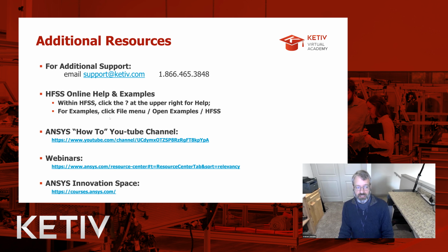And then in addition, I wanted to alert you to the HFSS online help. The little question mark at the upper right is very helpful. And there are also, if you are within HFSS, just in the file menu at the upper left, if you click on that and go to Open Examples and HFSS or HFSS 3D Layout, there are a number of example models that are there for you that sort of show you how it's done. So if you're looking for a particular type of antenna or a particular type of analysis, this is another fruitful thing in terms of taking a look at, well, what's the example model look like?